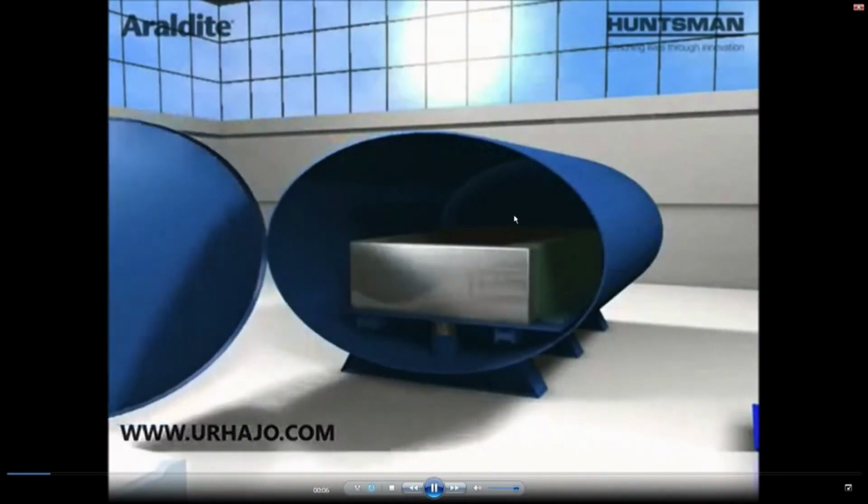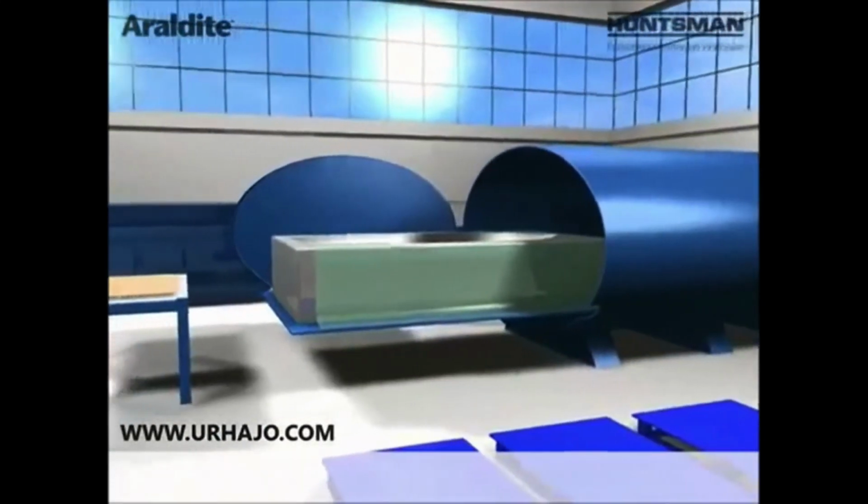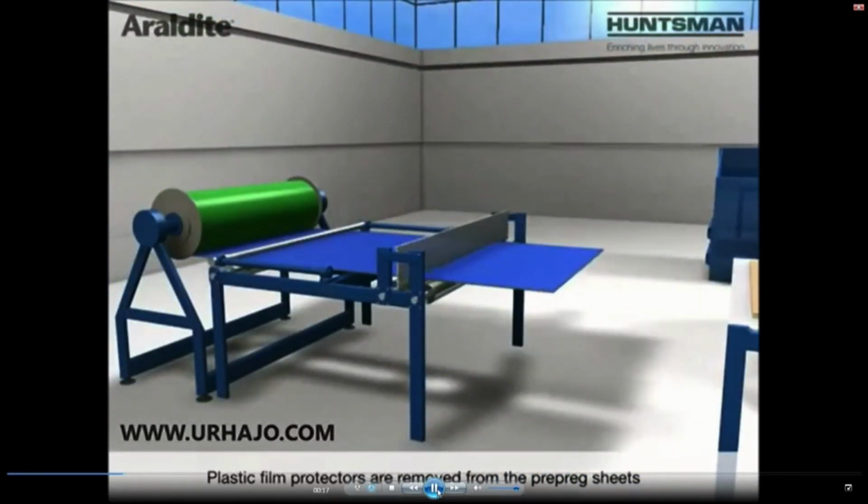This video we have already shared, available on YouTube. So, this is the autoclave, this is the mold of the final product that we want to produce. I will try to stop it in between to just explain. This is basically the pre-preg that is coming. This is the roll of the pre-preg, and the pre-preg is moving in this direction, and here we have a cutter which will cut the size as per the required dimensions. Now, let us start it.